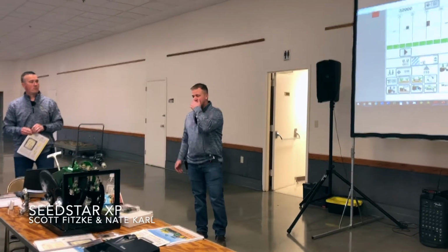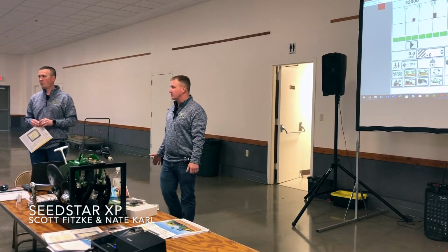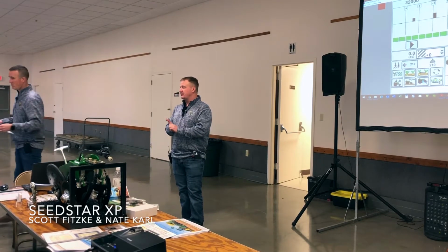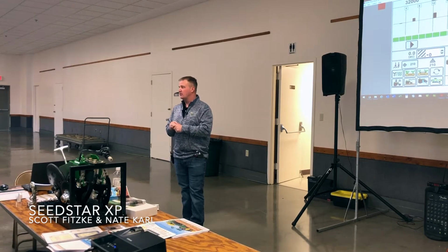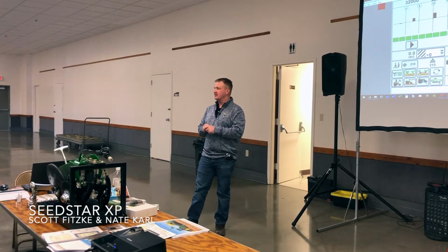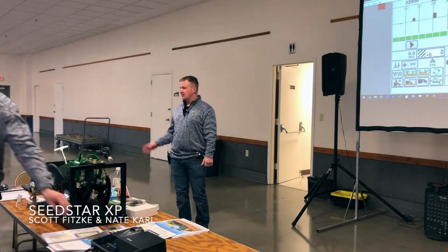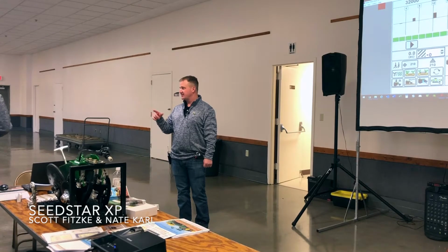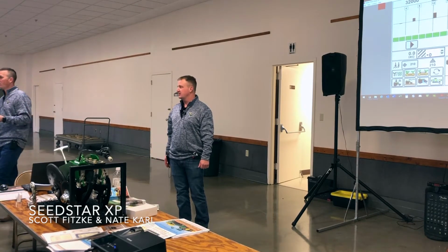Okay, starting off, this is a SeedStar XP class. So, rundown of what SeedStar XP is: basically you'll be able to get singulation, downforce, and coefficient of variation over what you would basically have with SeedStar 2. So it's a lot like SeedStar 2. Just make sure everybody's in the right class. You've all got that on your planters or are getting it or new to it.